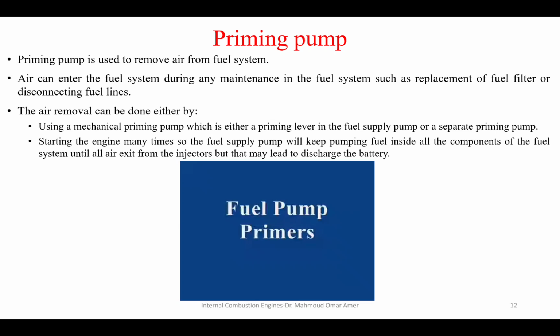But this method might work with small air amounts, but if there are large amounts of air inside the fuel lines, this method will be very exhausting on the engine starter, the battery, and might damage parts of the high pressure lines.